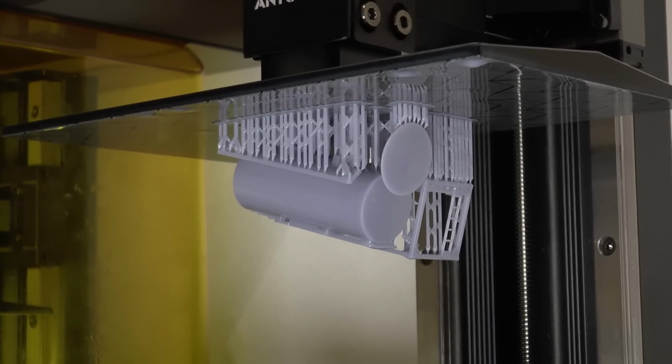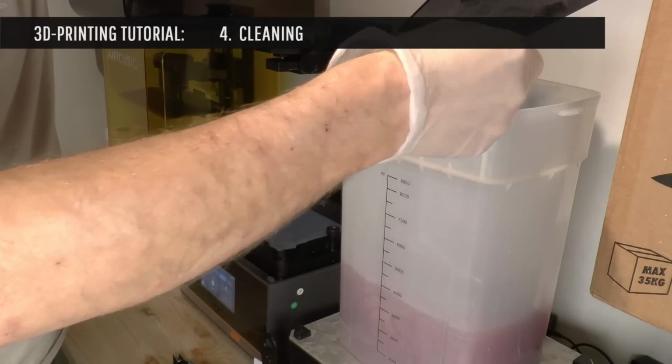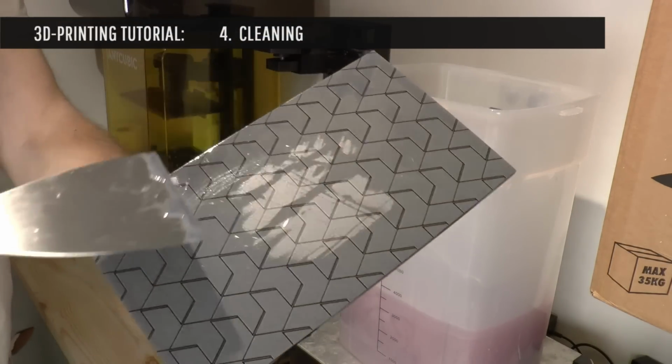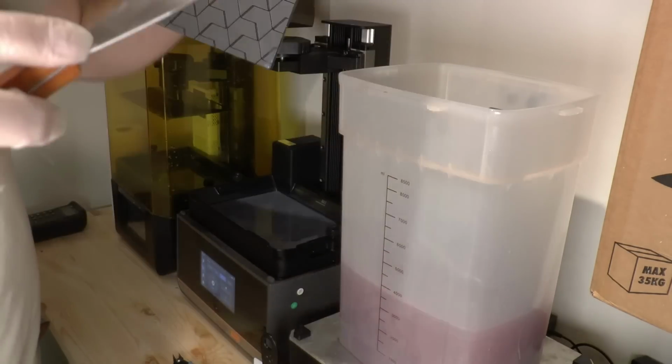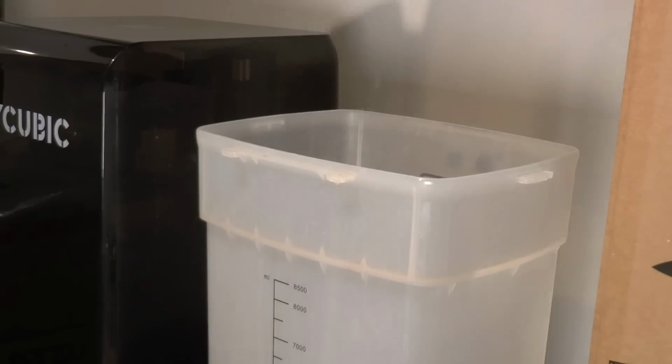And this is what it looks like when it's hanging there upside down in the printer. We're scraping the printout off into a bin of alcohol. I'm using ethanol here, and then I make sure that the print head is clean and thereby ready for the next print. Then I hang it back and secure it with a screw.